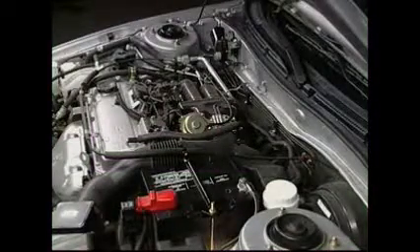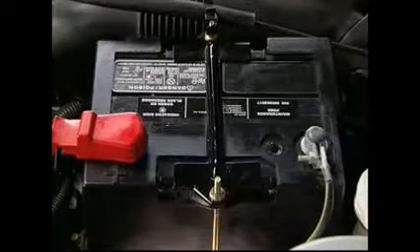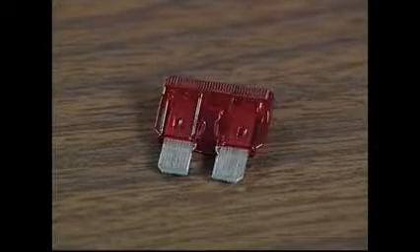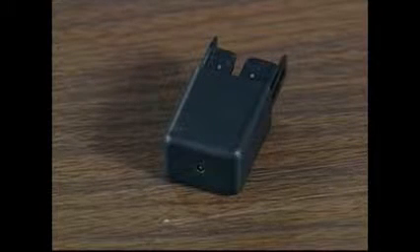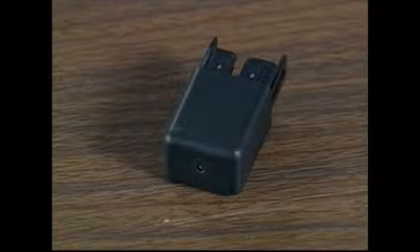In order for an electrical circuit to do work, there needs to be a source of voltage, a load, and a ground. In addition to the basic components of a circuit, a protection device such as a fuse or circuit breaker is required to prevent damage to the wiring in the event that there is excessive current flow. Most circuits will also have a switch that controls the flow of current through the circuit.